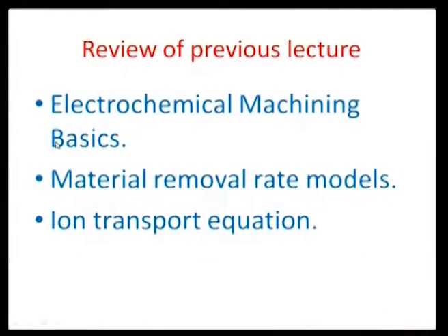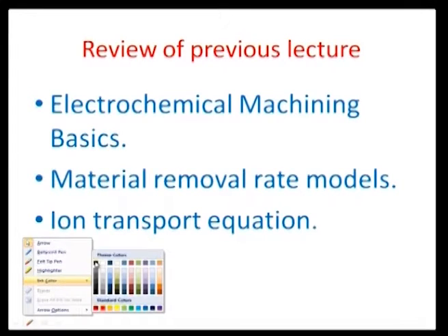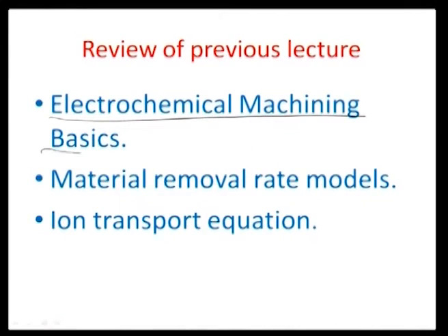So, we were talking about electrochemical machining, some basics and fundamentals. I would like to mention here that it is a process where the tool is made the negative electrode, the cathode, and the workpiece is made the anode. The choice of electrolyte is done in a manner so that whatever dissolves off the anode goes as a precipitate into the solution and is circulated, so that there is no deposition back on the tool cathode, and this way the whole process is made amenable to machining of materials.